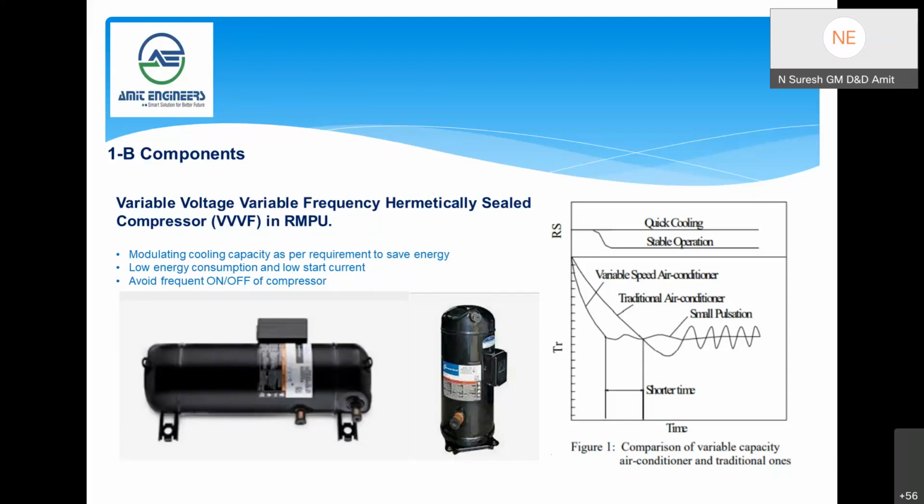How much is the mixing of the air? Like how much is the fresh air and how much is the return air? As I reviewed, 645 cmh is the fresh air supplied through one unit. I mean to say, is the same air being recirculated or fresh air? Partially. Out of 4400 cmh, 645 cmh fresh air will be fed always. The remaining air is recirculated inside the coach.